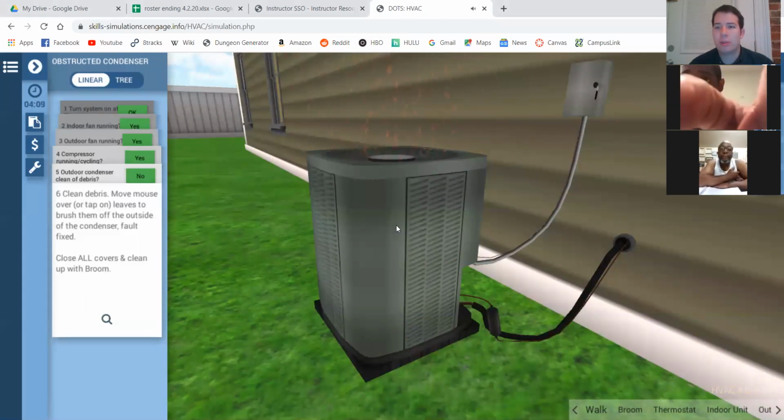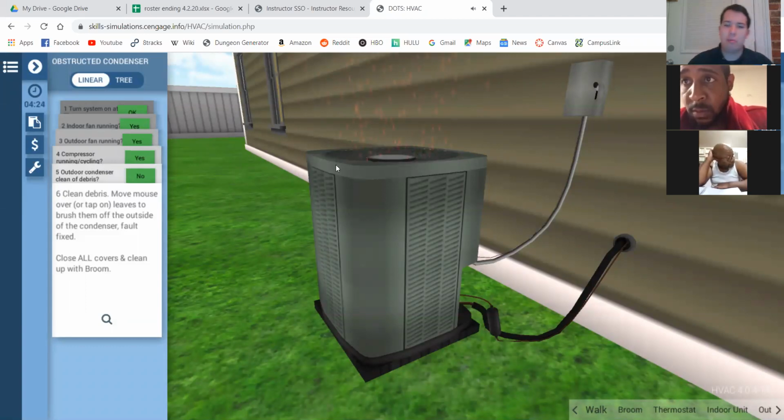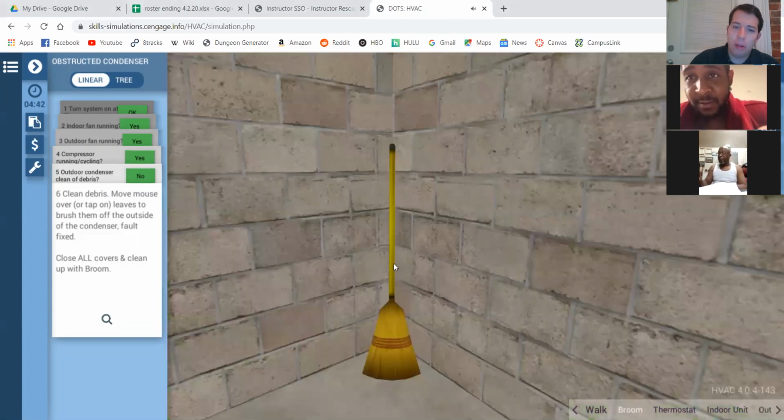Air conditioning, as far as the condenser coil especially, you'll spray these things down. The cleaner foams up, like if you ever put hydrogen peroxide on a cut and it foams up, that's what this stuff kind of does. But it really expands like crazy. The whole thing looks like this crazy foaming at the mouth, like a rabid air conditioning system, basically. And it pulls all of our nasty stuff to the front of that coil.